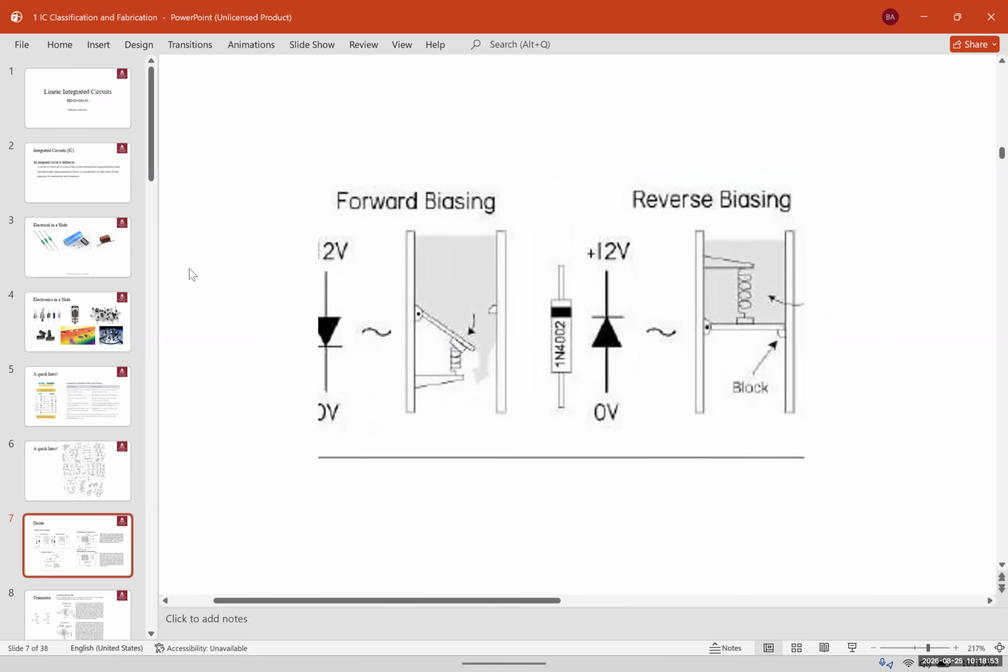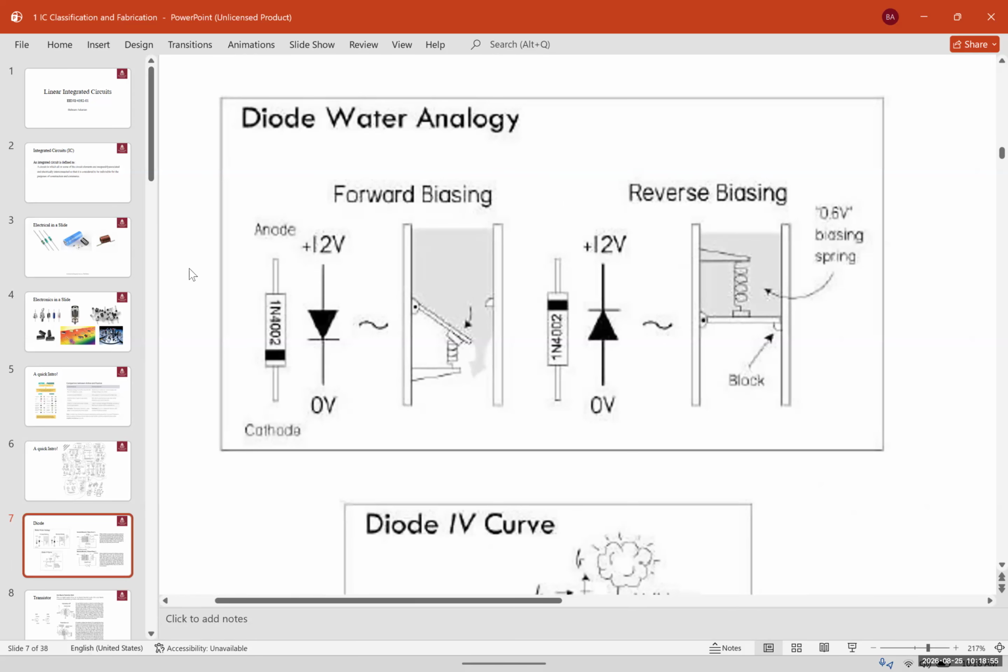And also we have a reverse bias as well, meaning in an ideal situation, a diode could endure any voltage in reverse bias. But in the real world, what happens if I put too much water pressure on the left from bottom to top? If I put a very high water pressure, what happens to the valve? It's going to break, it's going to explode. So that's a limit of diodes as well. In reverse bias, there's a limit on how much power, voltage, or current you can put in reverse.